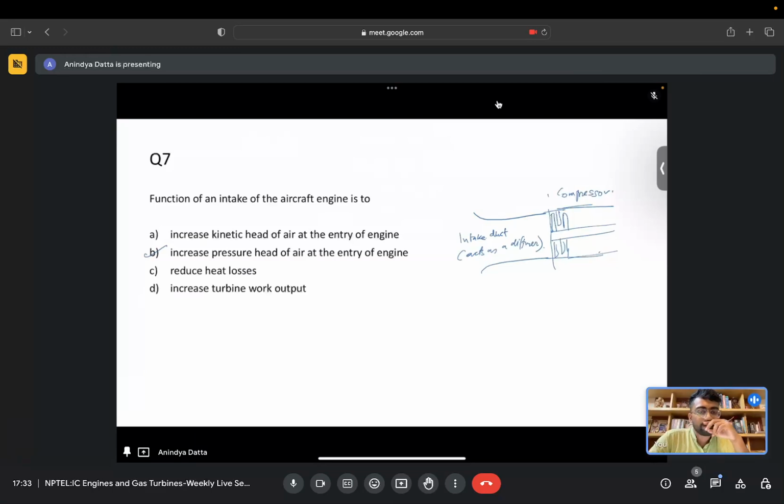If the velocity decreases, that is also beneficial, because if you remember the expression for pressure rise in a compressor, that depends on the flow velocity. Now if the flow velocity is too high at the intake of the compressor blades, the relative velocity component might also get high, and if the Mach number based on the relative velocity goes beyond 0.8, shocks can form on the compressor blades, and then there will be much more losses and the compressor won't work efficiently.